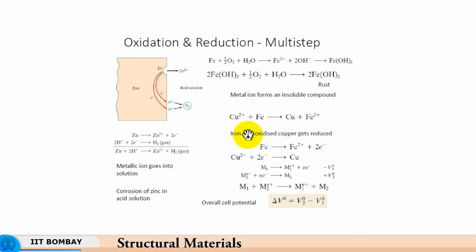You can have just one single piece with different kinds of properties, some small variation, residual stress for example. The part does not even have to get loaded. Even the presence of a small amount of residual stress can result in that area getting corroded faster as compared to the neighboring area. There are umpteen reasons how residual stress can be generated.